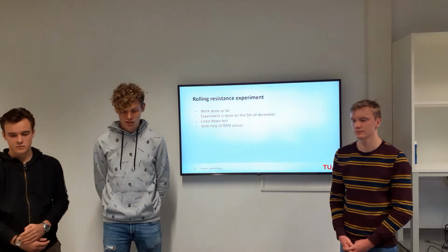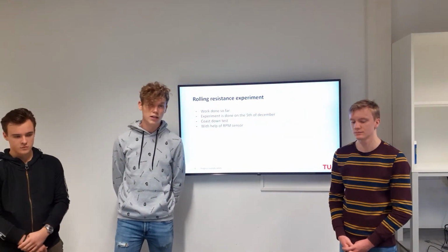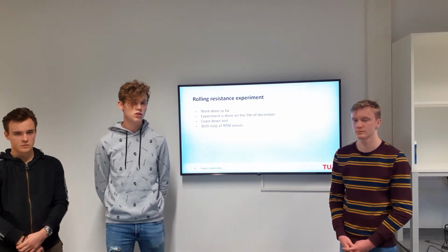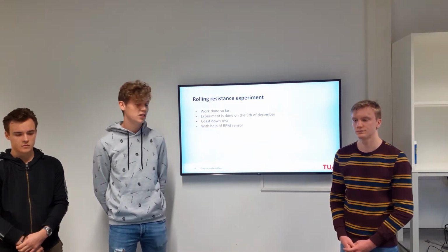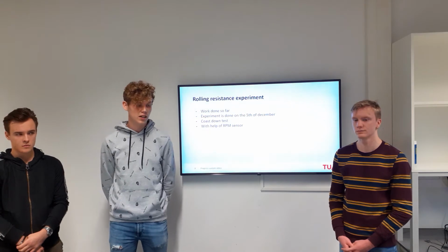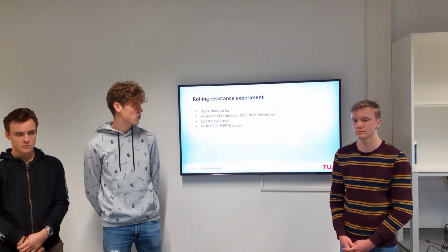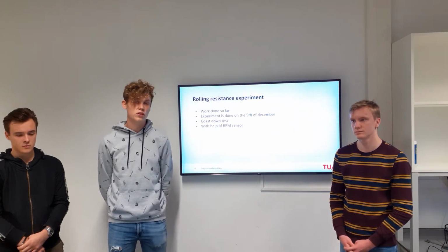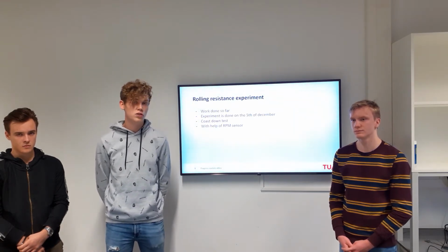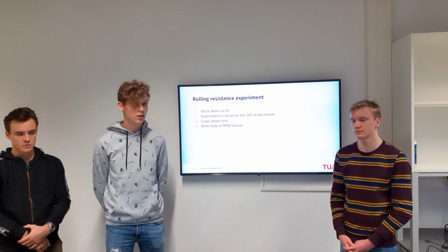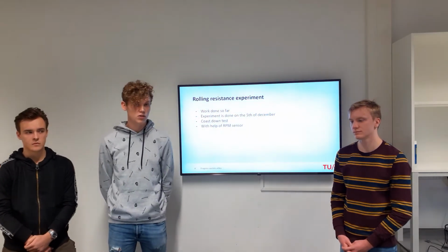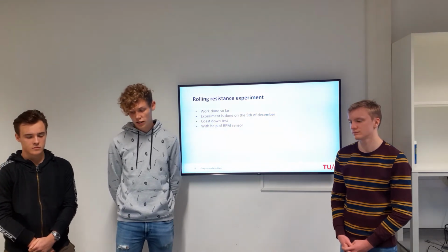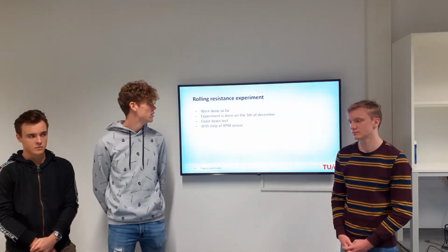A coast down test is basically implemented by just giving the car a certain speed and then letting it roll out to see how much this deceleration is. And from this deceleration we can calculate the total resisting forces. And when we get the results of the air drag test of the wind tunnel, then we can subtract those forces and then we're left with the rolling resistance forces, since there's no gradient on the Markthal where we're going to test, do the experiment and also do the final challenge day.